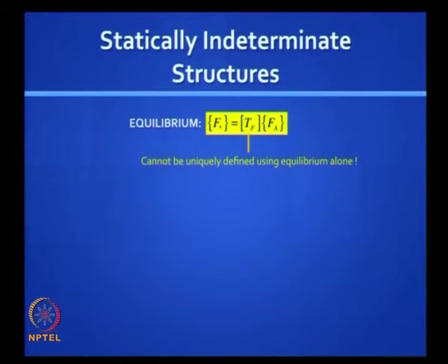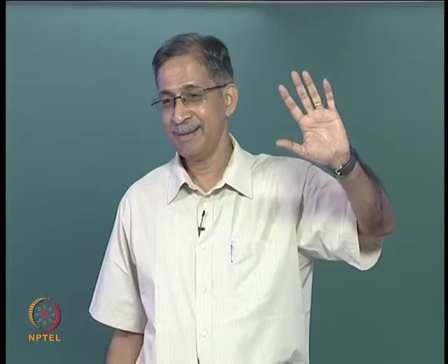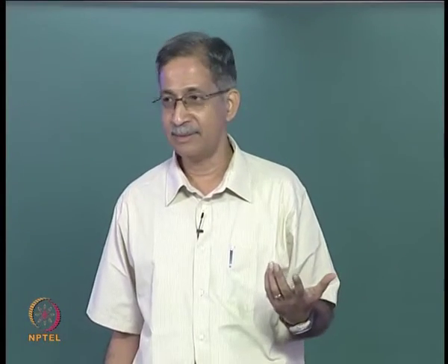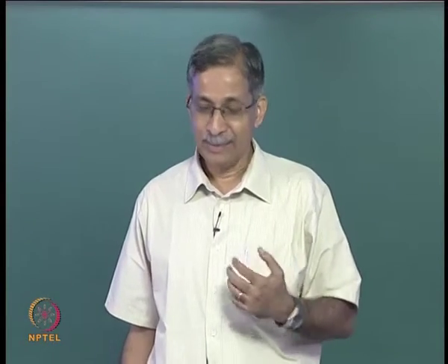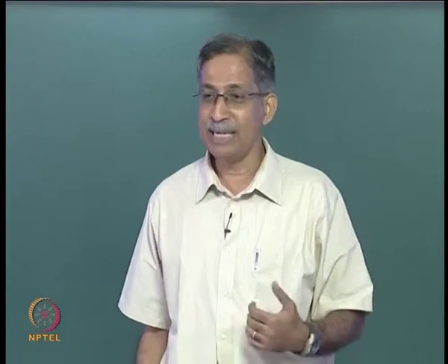Previously that TF was unique, you apply F1 equal to 1, the bar forces are unique, but now you apply F1 equal to 1, you have an indeterminate structure, you do not know the answers, you got it. So we take advantage of the fact that a unique TF can be done. So what we do is we reduce that structure to a statically determinate structure and play our games with that primary structure. Is it clear?